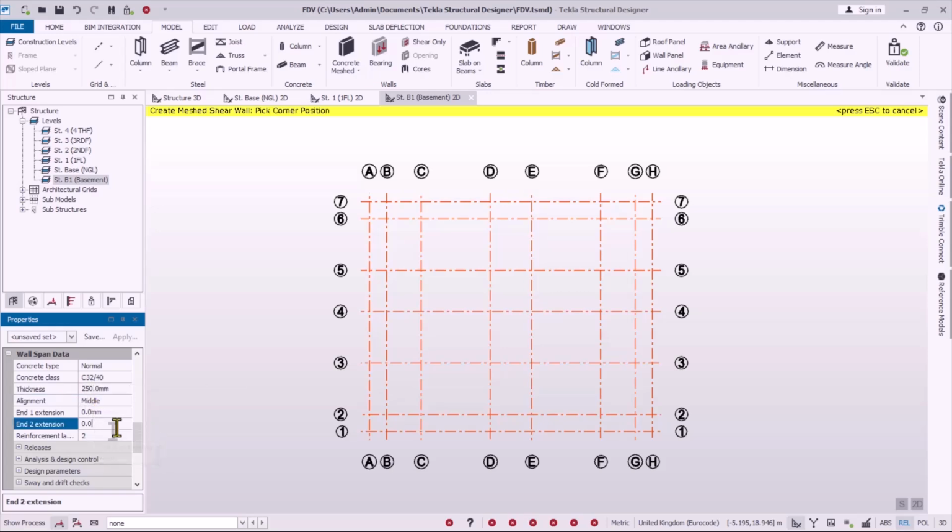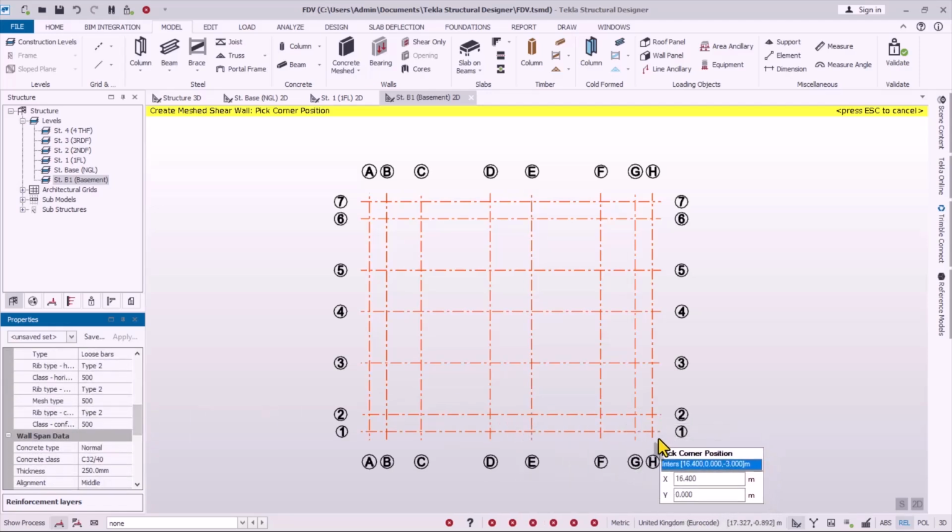All right, then we scroll down. The nominal cover from here is 25. We are going to be using 30 right here. All right, just like this. So these settings are good. Every other thing, leave it as it is. So we want to start to model the basement.